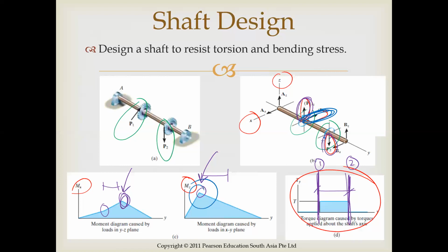Well, problem is, if you make it capable of absorbing that much more energy, what would happen is things would run into it, and then instead of absorbing, they would ricochet up and over and end up causing a worse collision because it was too rigid now. So he was saying there is no factor of safety when it comes to absorbing energy. You want it to be right on. So depends what you're doing.